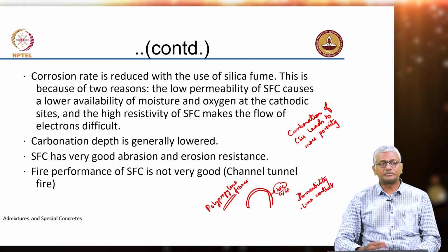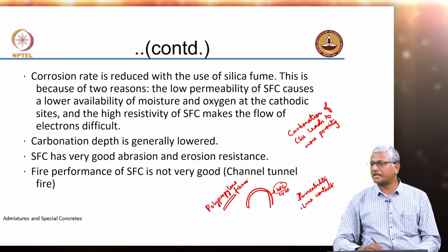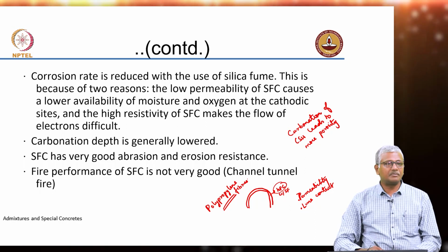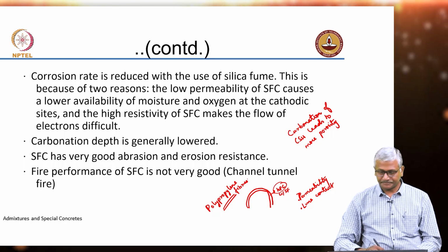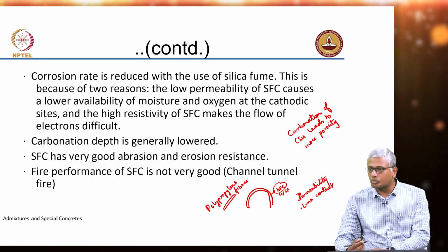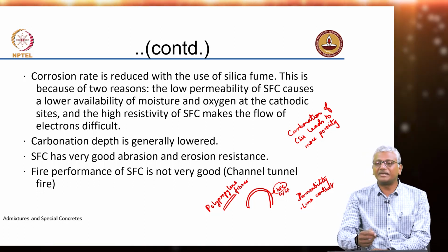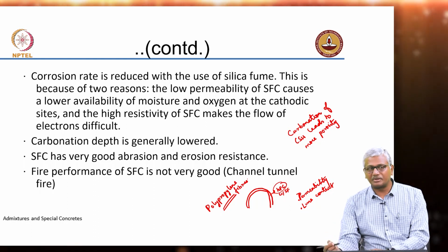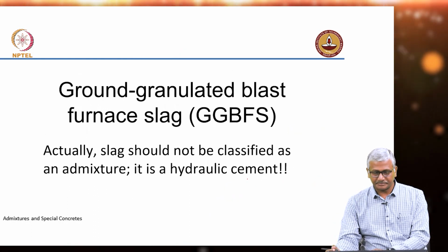Okay. But with silica fume, we can expect that there's going to be very high pressures because of the steam generation inside the concrete. Of course, that doesn't mean we can start making concrete more porous, right? It's only in an extenuating circumstance like a fire where we put fibers inside the concrete.